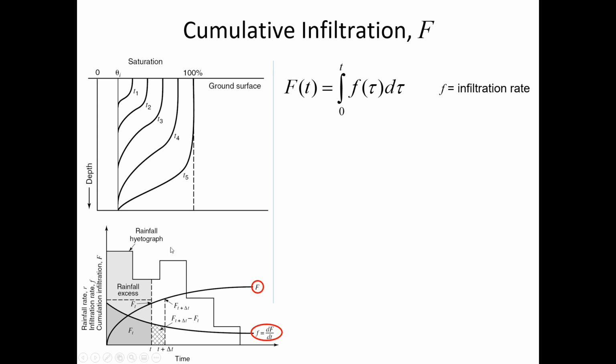And this is a really important figure. We've got a rainfall hydrograph, which you've seen before, these hydrographs. So here on the vertical axis, we're representing several things simultaneously. The rainfall rate, and that would be maybe inches per hour. And so remember, this could potentially be a storm that was like 2 inches per hour for 1 hour, and then 1.5 inches per hour for an hour. And this looks like maybe 1.7 inches.